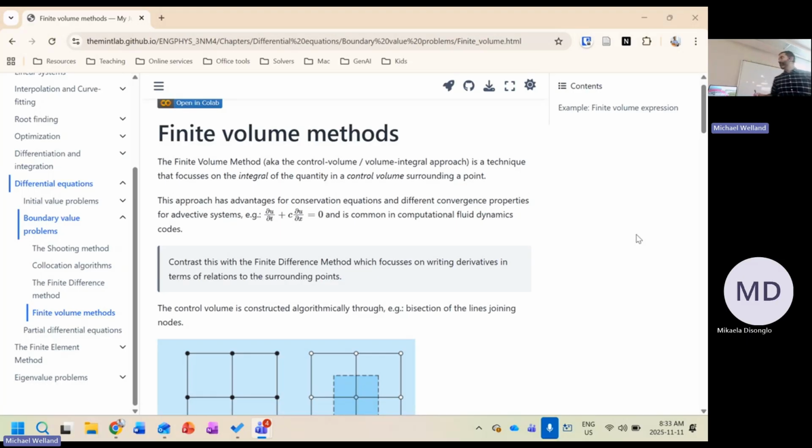related to finite difference. The way that finite difference worked was, let's say you're in 1D, you're implicitly mapping out some kind of shape of your field, right? Temperature versus X. Okay, and what you're doing is you're saying, okay, at this point, I have some kind of finite difference. So you want to solve heat transport, say. Okay, so this needs two gradients. You need this gradient and you need this gradient, right? How do you get those gradients?